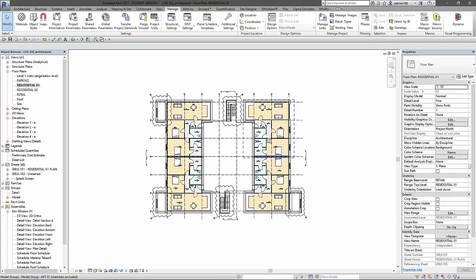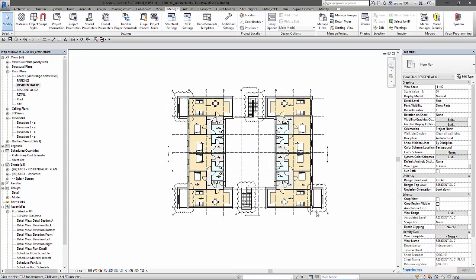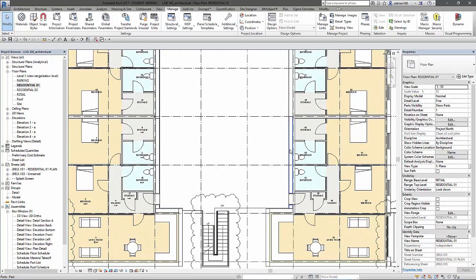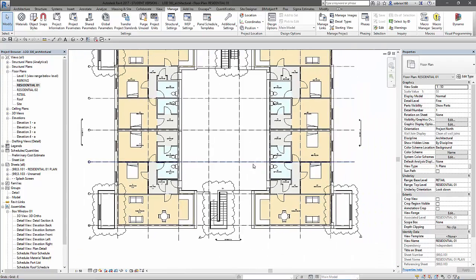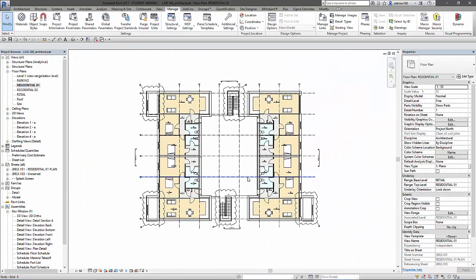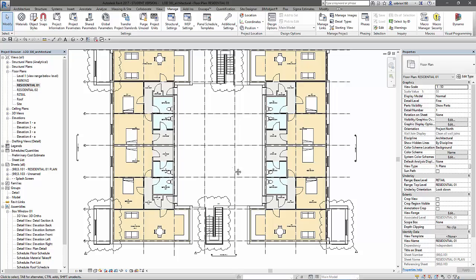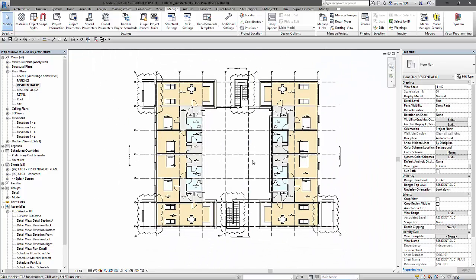So at the moment I've given all the elements the same time reference, but you can split them up into, for example, if we're dealing with the insulation layer, 120, 121, 122, and so forth. If you want to be more precise in terms of the construction process when we get to the timelining, because that is the way to timeline according to locations in the plan view, because the standard timeline just runs horizontally, level by level,